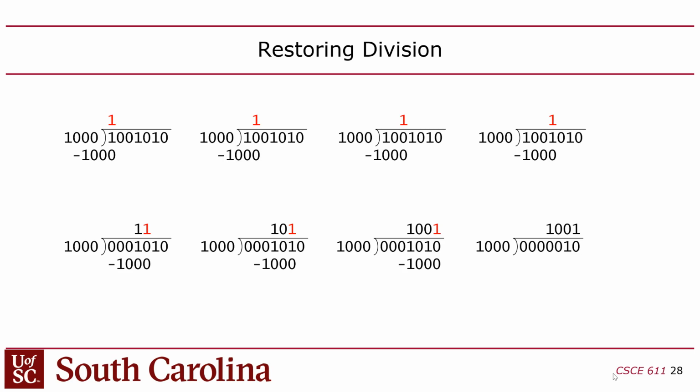Well, it's doing trial and error because as a human being, yeah, you would skip those steps because they would look unnecessary, right? But the hardware doesn't know that, so it has to go through every possible position. It has to take the divisor and subtract every possible position of that from the dividend. A 1-bit divisor could just be 0 0 0 1 instead of 1 0 0 0. Yeah. In which case, you could have actually had a 1 all the way out there. You know what I mean?